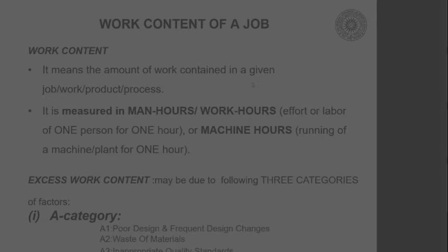Okay, then the required tooling will be there. Then to set up the tool, to load the tool, to load the workpiece, and start the machining job, measuring the size in between, and finalizing the size of the shaft. So these are the work elements. So they are contained in the work. So we call that work content.